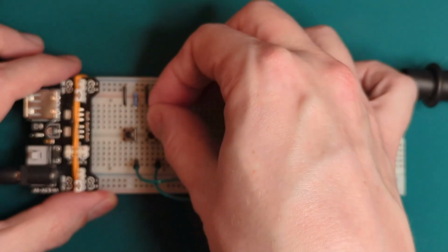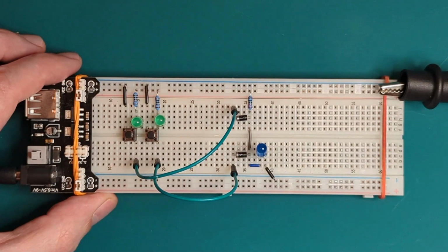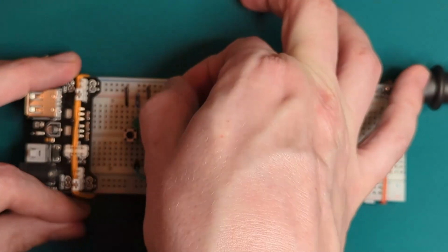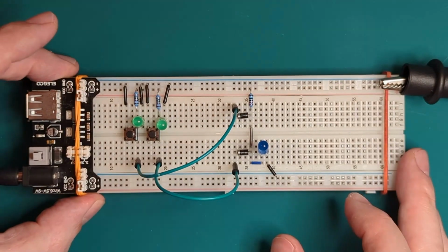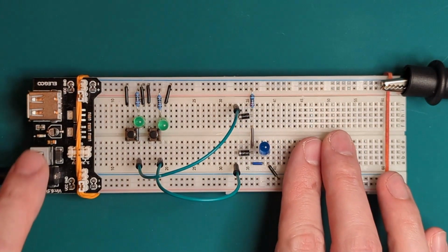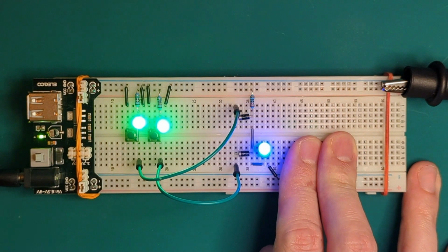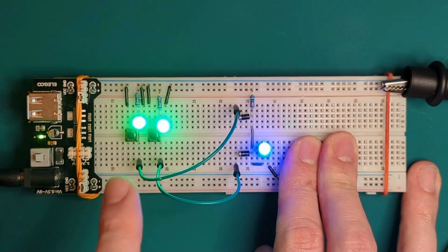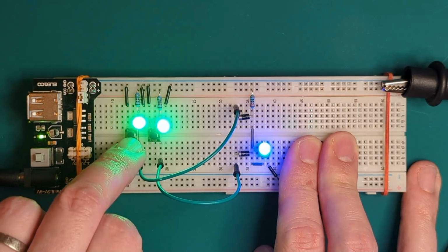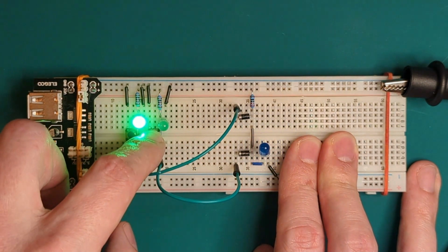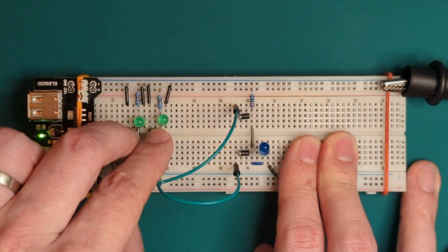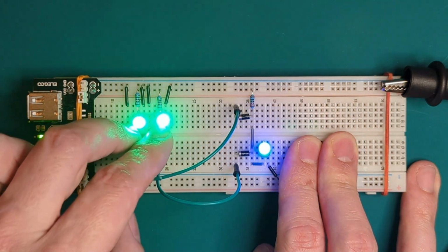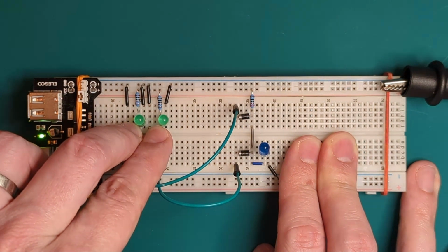So that's connected to 5V. Let's add some LEDs. And LEDs should go to ground. Okay, let's power this up. Now it seems we're getting the right result. Output is high only when both inputs are high, which is both buttons are released now. And if I press any of them, or both, the inputs go low and the output goes low too.